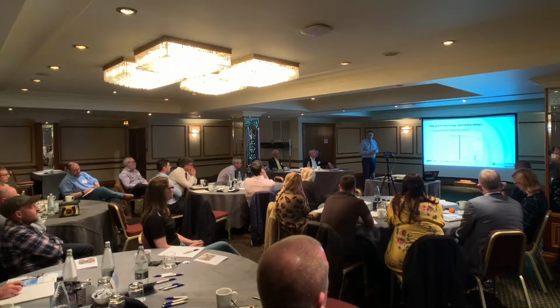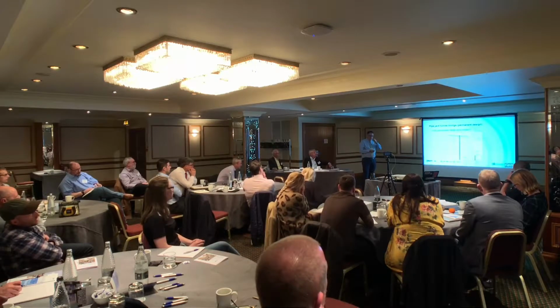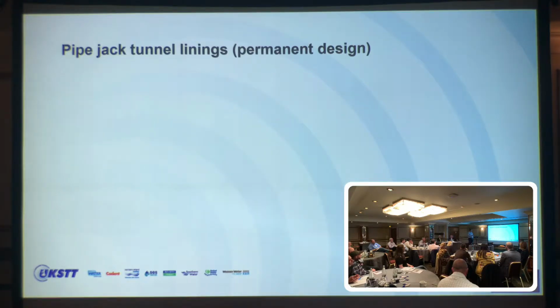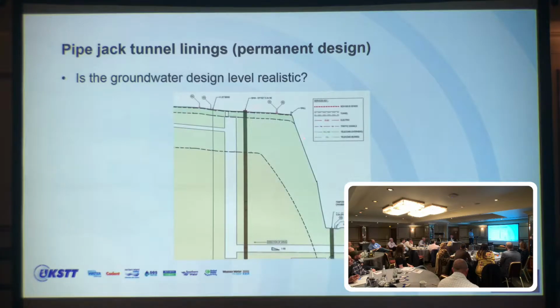Groundwater is very, very important. Ground load can often be considerable. It's certainly probably one of the dictating factors of load. I've put this photo here, and this is a job that I was involved with a few years ago now. It's a water company job. So the water company, as many of the water companies are, specify that the design groundwater needs to be at ground level for the shaft.